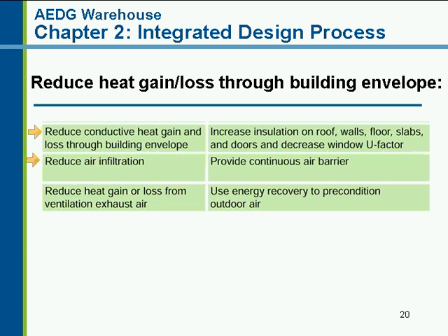And people sometimes think that they just need to seal around doors and windows, and those are important things to do. But you need to be caulking sill plates. You've got loss coming through electrical outlets in the walls. People have situations where they've measured a lot of air leakage going through interior partition walls up into attic spaces in the roof. So you really want this continuous air barrier to go around all the wall surfaces and whatever ceiling or roof surfaces are enclosing the conditioned space.